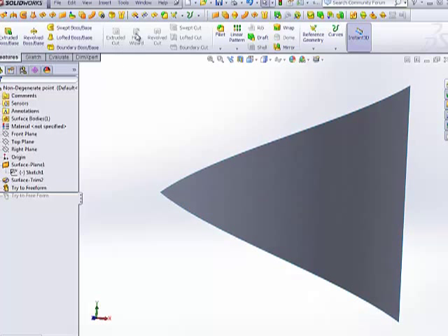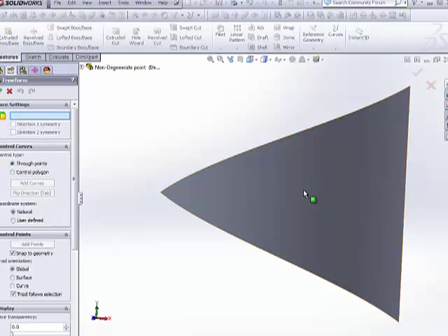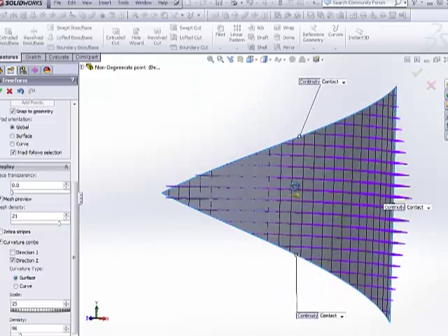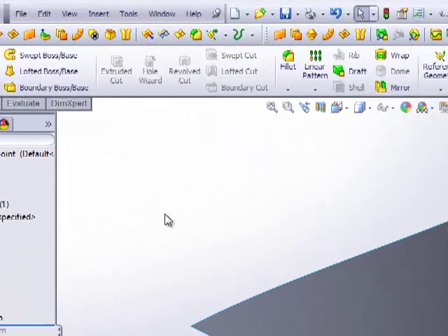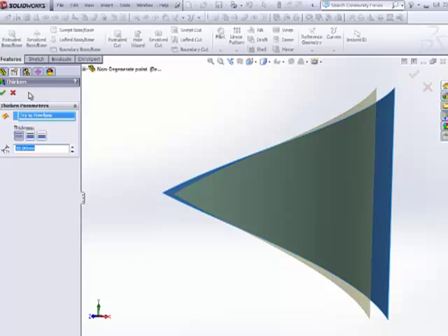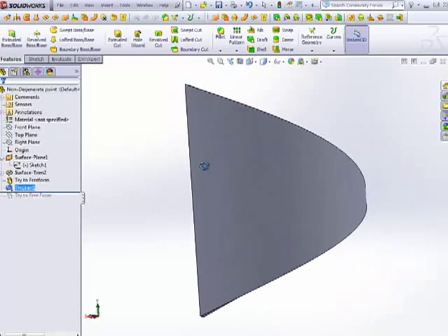Now, if I try to use a freeform feature on this surface, I have no problems. You can see I have all the tabs open, and I have the mesh showing lines that are parallel to one another, and they all extend out and are just trimmed along the edges I had trimmed. When I go to thicken this or play around with it, it's going to work just great. It's not going to give me any problems, unlike other surfaces. You can see it thickened just fine.